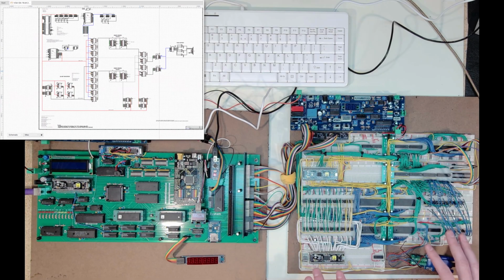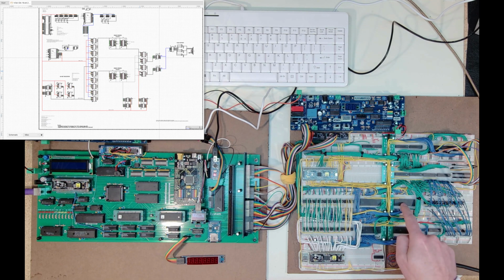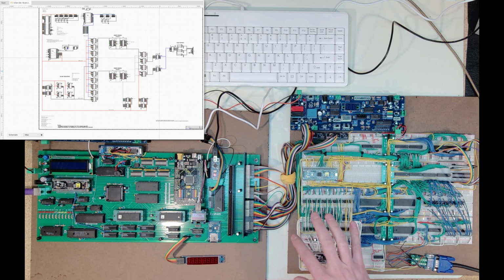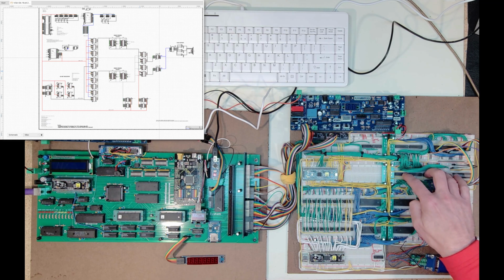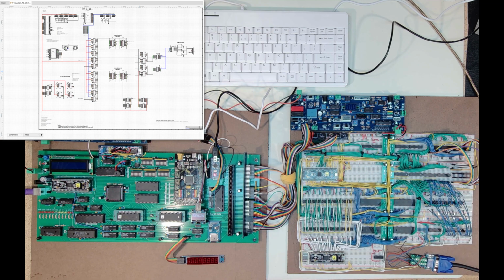So looking at the breadboard itself here, let me just point out where I'm sitting with this. So this was frame 0. These were my multiplexers coming in. I've now connected frame 1, the pair of static RAMs, along with their multiplexers. All of the appropriate addressing signals coming from the 286 are making it to both sets of multiplexers. The VGA out circuit, all of its addressing is going to both sets of multiplexers. The output of frame 0 and frame 1 both go through their appropriate transceivers to get back to the data bus on my 286.